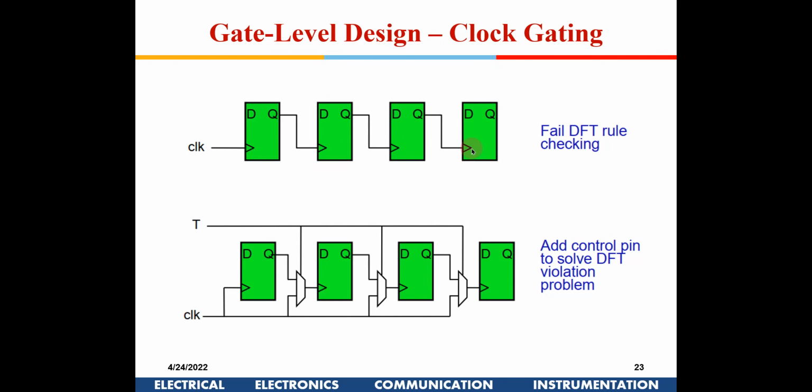Suppose you have implemented a counter, where the output Q is given here, the output Q is given here, and the output Q is given here. This also becomes a counter. You can implement a counter here, or you can have a synchronous counter also, where the clock is given to all the flip-flops, but in a synchronous counter generally the power consumption is higher, whereas when you make an asynchronous counter, then the power is much lesser.